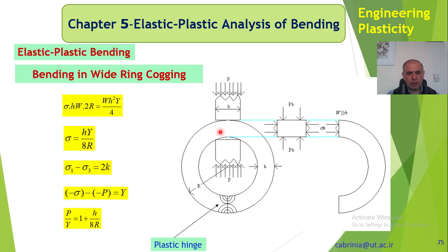Or in other words, because we are pushing the material in here, applying this load, the material must flow because it has reached its yield point. So which direction does it flow? In a direction which is easier. So the material flows that way, because it cannot flow perpendicular to the screen, as the dimension perpendicular to the screen is thick because it's wide, and therefore it's difficult for the material to flow that way.